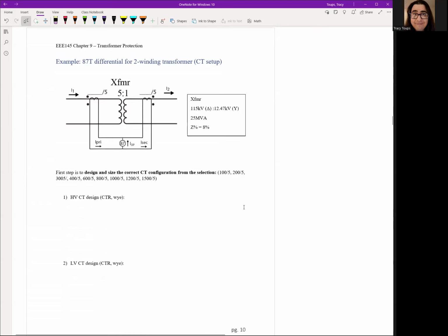So with that being said, we went over a couple of main points about choosing the correct CT ratios, being a little bit constricted by the design of CTs, and then having a mismatch problem. And then the second step would be finding your relay taps to then correct this mismatch. So here we typically take our 15-20 minute break. I want you to do some exercise in the middle of class.